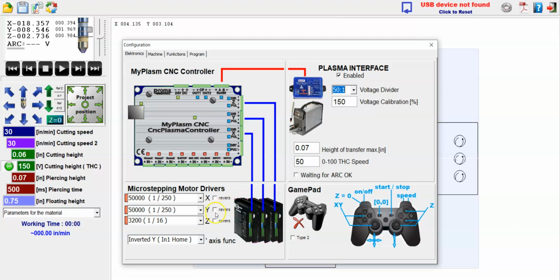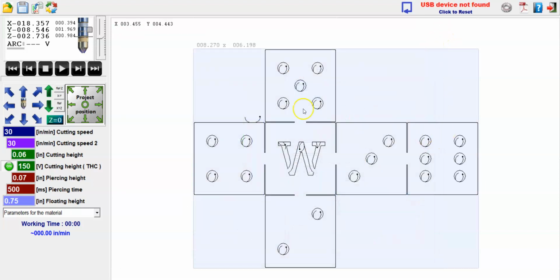If it's not moving away from you, your y-axis may be backwards. So make sure that reverse is selected if your y-axis is running backwards. Similarly, your x-axis, your left and right, if it's going right when you press left on your keyboard, there's definitely a little bit of a problem there, and we want to avoid that. And by reversing the direction, we can do that. So keep that all set up for you here. So you'll install the config, you'll do those, and we will be good to run.